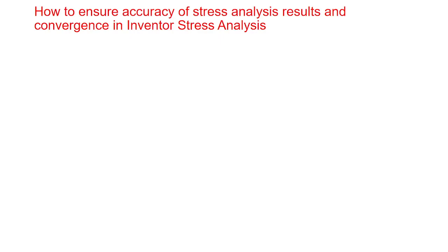Not an infinite number of elements, but using more elements we can find the stress value sufficiently accurately. In doing this, we start with a coarse size, and then in every successive repetition we decrease the mesh size, and then make a comparison.